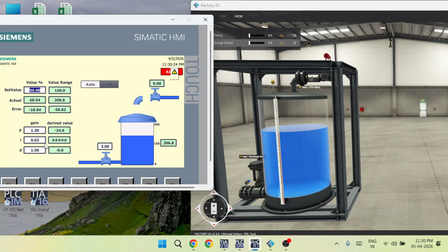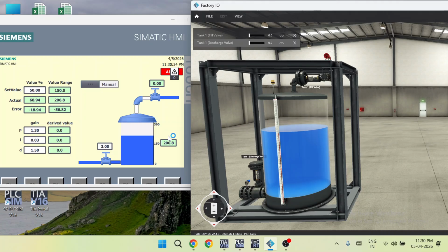It's a fully animated display and tailored in the three versions, as the input of the sensor will be about 0 to 10, and our entire PID will take data in percentage. So first of all, convert the actual value to percentage, and for showing it at the HMI, as the tank is from 0 to 300.